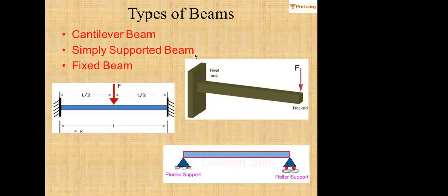So all the action is going to be at this fixed end. It's like wherever you are providing obstruction, you have to solve all the reactions along that obstruction. So in this case, we are obstructing it on its one end. So this is what you call a cantilever beam, right?